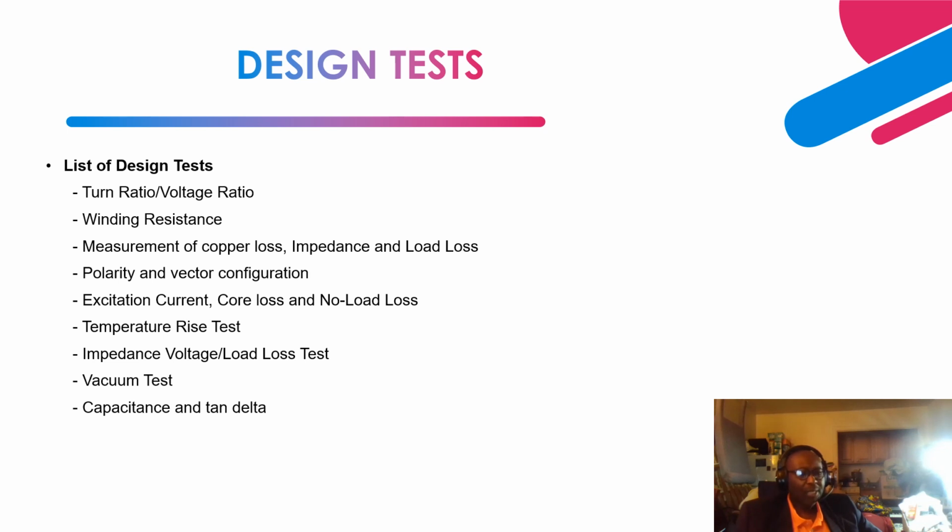As this paper insulation deteriorates, once the capacitance is formed with this paper and the oil, definitely the capacitance is going to change. Right? So the testing itself gives us an indication of the capacitance change. For a new transformer, after the design test is performed in the factory, and in the future you perform the site acceptance testing or the routine test, the change in capacitance shouldn't be more than plus or minus 5% for a new transformer.